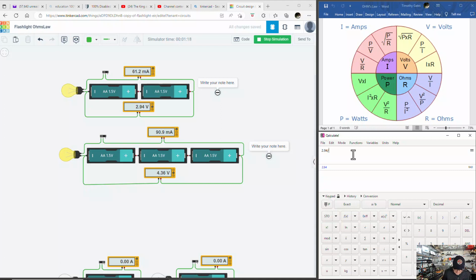But we're going to write that as 0.0612. So 0.0612, see the decimal place is moved over 3 places. So it would be 0.0612 amperes. But it's written in milliamps because that's the way it's displayed on the meter. The meter doesn't have enough positions to put 0.0612. So it has to move the decimal place over and then make it milliamps.